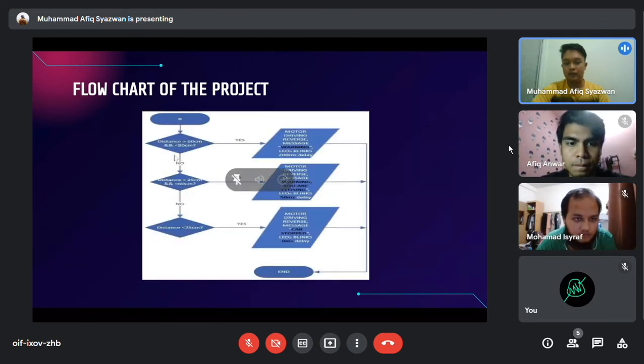Then when the distance is more than 60 centimeter, the motor driving will reverse and a warning message will appear at the display panel. And if not, when the distance is more than 25 centimeter and below 60 centimeter, the motor driving reverse, the message will warn you that the car is closing, and the LED will blink with 50 millisecond delay.